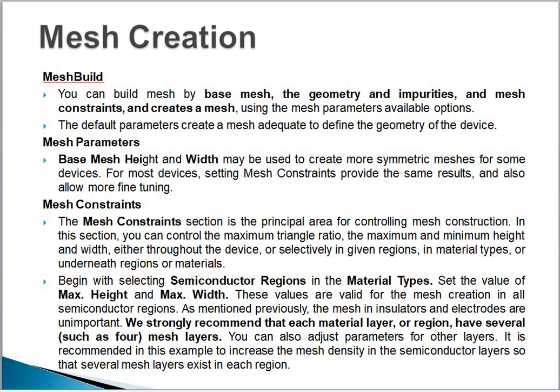How to define the mesh parameters? Base mesh height and width may be used to create more symmetrical meshes for some devices. For most devices, setting mesh constraints provides the same results and also allows more fine tuning. Mesh constraints are very important to define a mesh in DevEdit. The mesh constraints section is the principal area for controlling mesh construction.